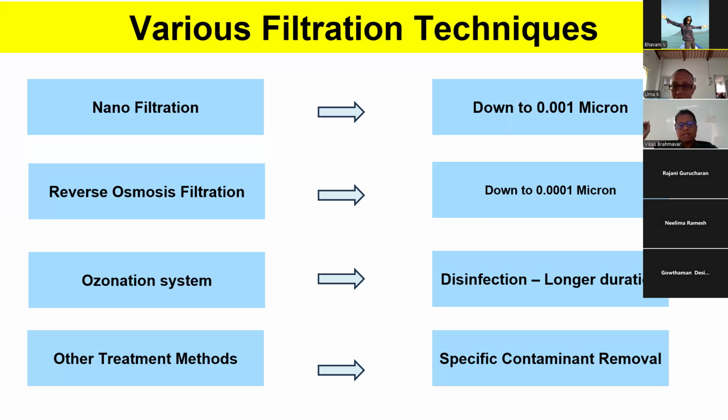So the outlet of the RO has a lower pH. What happens when you remove most of the minerals and the water comes out into the air? From the air, it absorbs CO2 and becomes carbonic acid. When carbonic acid is in the water, it will reduce the pH. Any acid in the water will reduce the pH. So there will be a 0.5 to 1 pH reduction between in and out, based on your incoming water, the CO2 level in the water, and atmospheric CO2. There will be a reduction in pH after RO. So that is a bigger problem than the salt reduction.